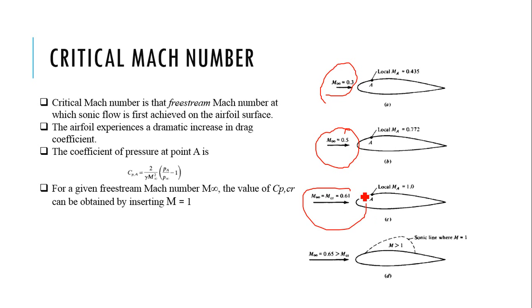So we are picking a point over here. That means when the Mach number is 0.3, somewhere over the airfoil, as we discussed in our linearized velocity potential, the free stream Mach number will change because of some increment in velocities.